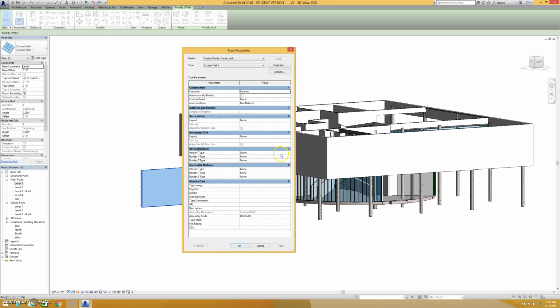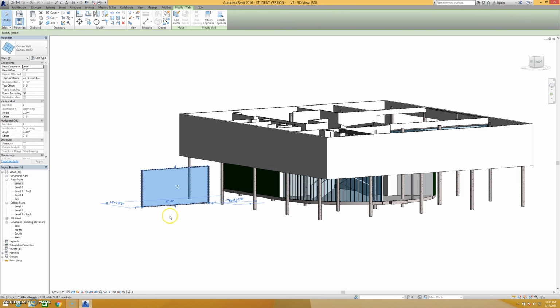and I have the option to go in here and change spacing and add things and specify my mullions. And I am going to specify mullions really quickly. I'm just going to do these 1.5 by 2.5 rectangles. But what I'm going to do in this case is not actually specify any standard grid pattern. I'm going to leave it completely blank. Okay. And I should duplicate this while I'm doing this actually and call this something like Curtain Wall 2. That works for me, just as a best practice. So I'm going to hit OK.